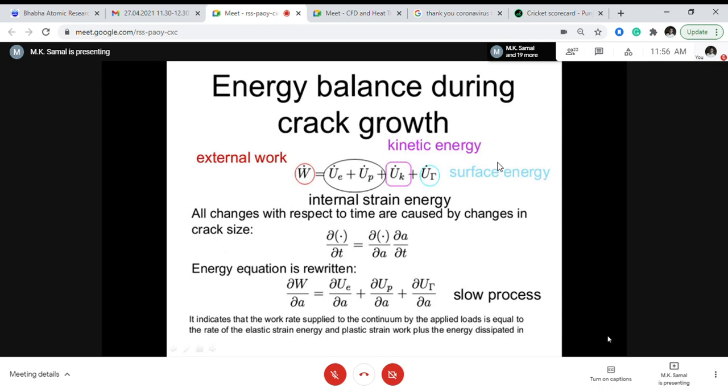So the concept of stress intensity factor is that you don't look at the stress at the crack tip, but you look at the value of the stress intensity factor, which is something called a crack tip loading parameter. Okay, so instead of using a localized crack tip stress as the design criterion for fracture mechanics, it is more important to evaluate this stress intensity factor.